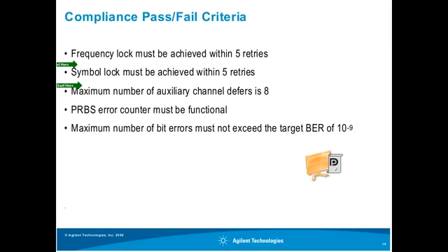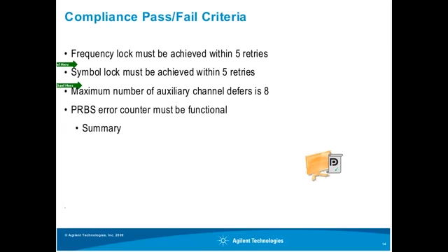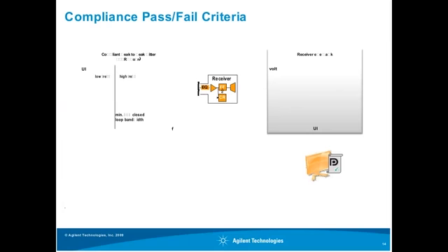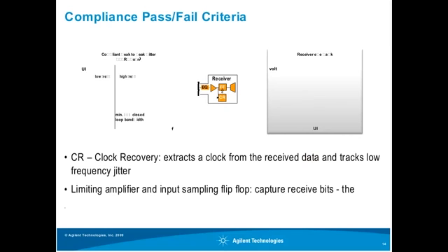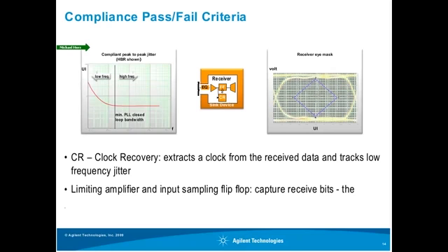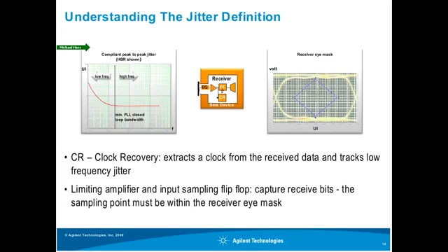Okay, so I mentioned I'm going to have a close look at the physical layer signals for receiver test. And I want to start with the definitions in the standard document. To understand those definitions, there are actually 2 graphs in the main specification that give the jitter numbers for receiver stress test. One is the jitter tolerance curve, on the left-hand side here, which shows the peak-to-peak jitter over a frequency range. You see the frequency on the x-axis and the peak-to-peak jitter on the y-axis in that diagram.